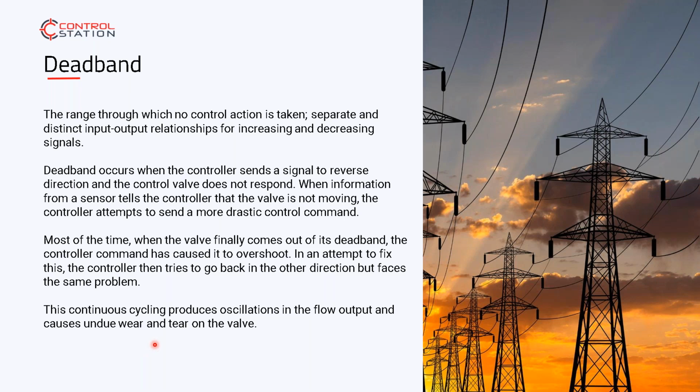a certain set of scenarios that you have set during your why am I here question. Why am I standing in front of this loop or this valve that's not performing like we did. We've all, well, perhaps I'm speaking for you, but I've regularly been in front of a control loop and says your PID is not functioning. In fact, the PID is probably the thing that's most perfectly functioning. It's the material and the equipment it's using which has started to struggle.